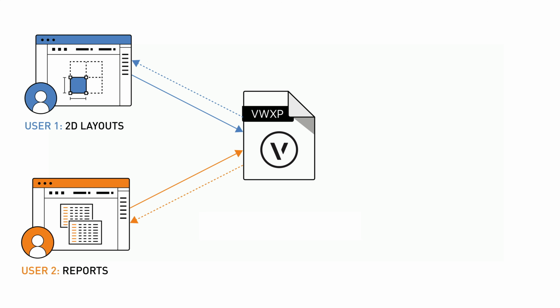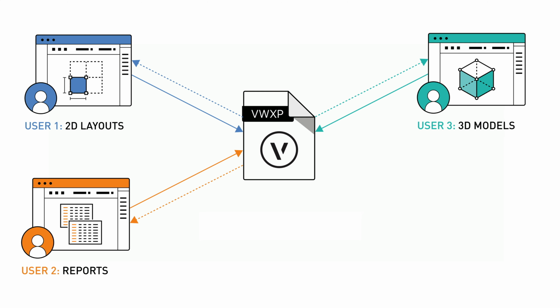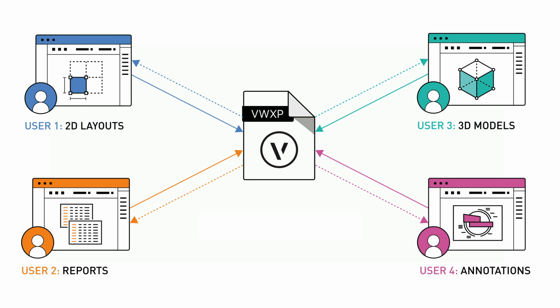for all to see. While a multi-user environment is not required for creating the BIM itself, such a system is well suited for collaboration on a BIM process because it enables all team members to work on the geometry and data of a common, complete project model. A good multi-user system will also allow you to set different sets of permissions for each collaborator and log comments about the work performed whenever part of the model has been checked out. All of these contribute to robust control and communication during design collaboration.